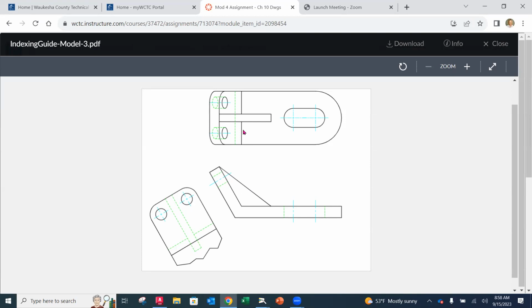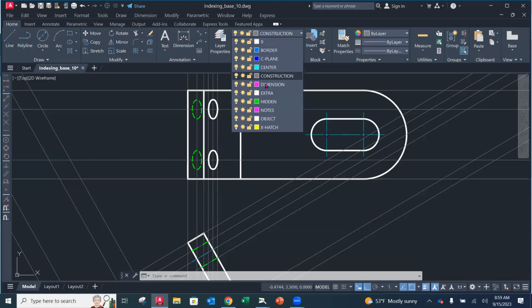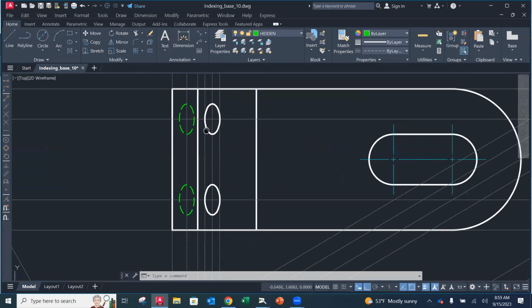All right. So you'll notice that we then need to connect those ellipses because there's edges that go there. So we're just going to stay on the hidden line layer. And we are going to go to line, and this is an intersection to an intersection or perpendicular. I'm going to do it for all of them. And then I'll reselect and change the properties so that they all are at that 0.375, which was what we used for the ellipses.